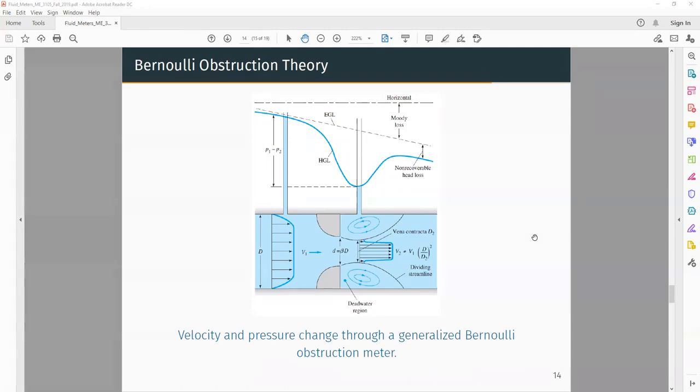And say we have a pipe diameter of capital D, and it is forced to flow through an orifice of small d, and the ratio of small d and capital D is actually beta. Fluid is flowing at a velocity v1 through the larger opening, that is the pipe, and fluid is actually flowing at velocity v2 through the vena contracta.